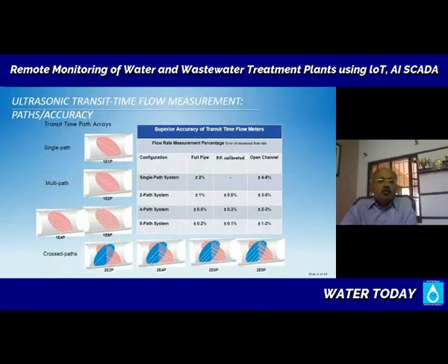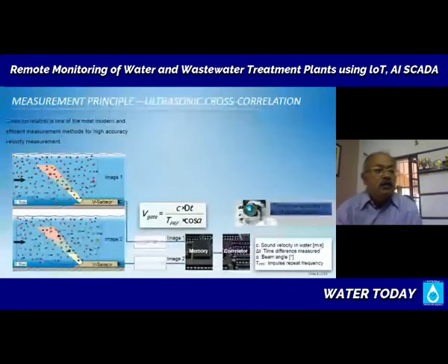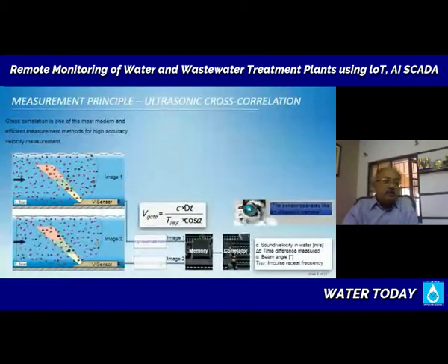And of course, earlier the cross correlation sensor. Here in this slide, you are able to see embedded particles. Like you have raw water coming from a river. Then you have some suspended sand or some pebbles or some embedded particles, sometimes some biological life that comes. This device is able to track the movement of specific particles and then see how much the particle traveled at a specific time period. So the particle is traveling with the velocity of the pipe. So by measuring the particle velocity, it is able to compute the pipe velocity.